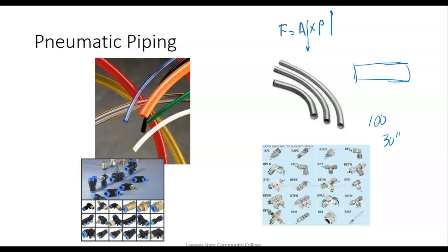And then, of course, there are some other advantages. You have more control over it because hydraulic fluid is considered to be incompressible, which means you can control the speed precisely. If you had a hydraulic motor, you could control it a lot more precisely, and the speed of the pistons as well.